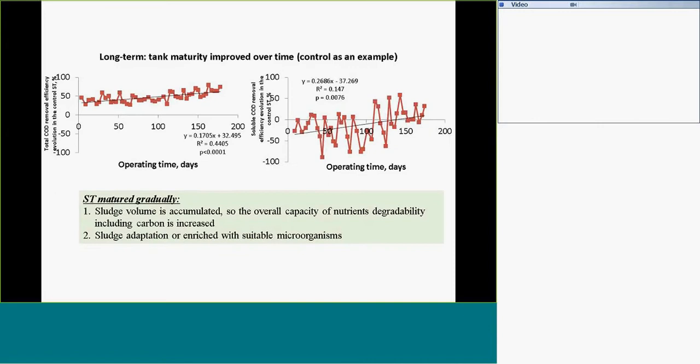And then we monitor the water quality in the influent and effluent to see what happened. And we see the gradual maturing of the septic tank. And even after like 209 days, the septic tank is improving itself in terms of the COD, including total COD and the soluble COD. Amazing thing.